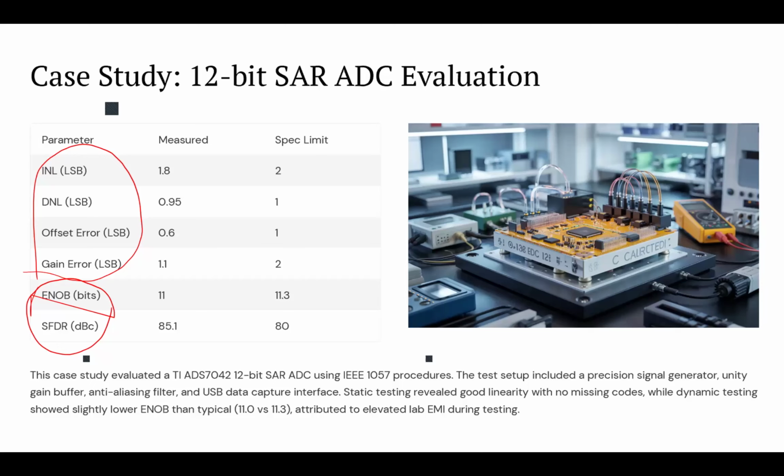Now, what does that mean? That means this converter reproduces analog voltage as a digital value, not perfectly, but faithfully and reliably. You can rely on that. It does not skip any codes. It has a relatively good linear transfer function, and it's well behaved.